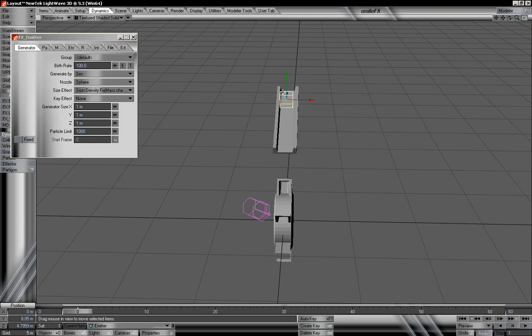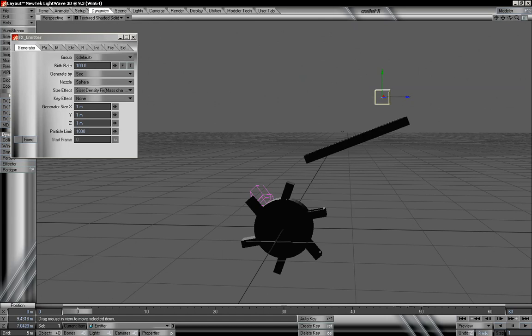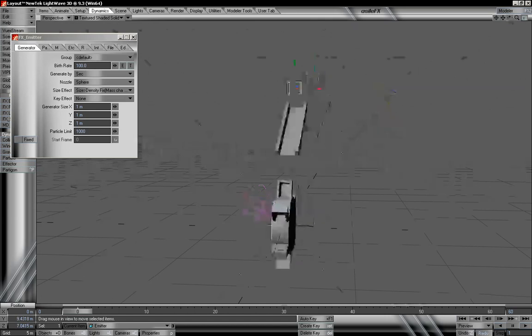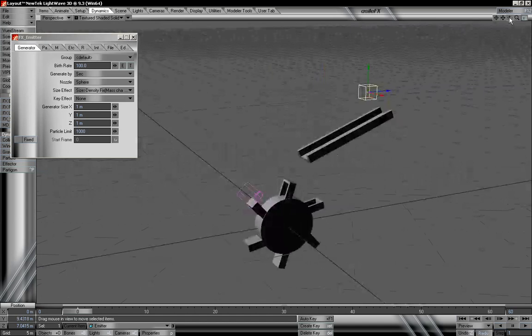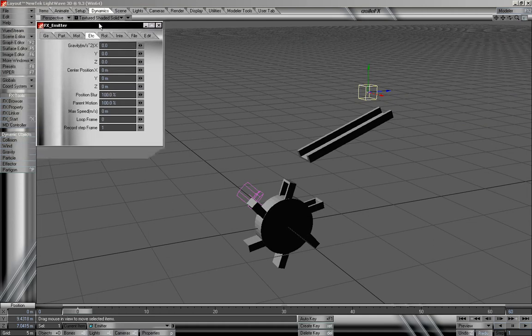We're going to have this just dropping onto our slide object. And we're going to use the global gravity option of our emitter itself and not a gravity object separately for the group. Let's go ahead and select -2 for our Y gravity.